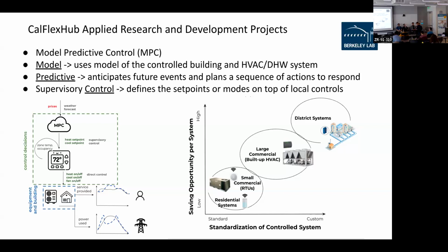So I put the graph here because I think it's important to understand that MPC in this case is sending set points to a lower level controller, which is represented here as a thermostat. And the controller controls the HVAC unit, sending direct commands to the components. So the compressor, the valves, and the other small components. So MPC can typically run every 10, 15 minutes and optimize these higher level objectives, and the lower level controller really controls the fine tuning of the equipment.